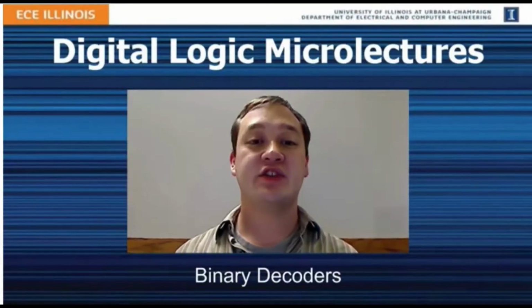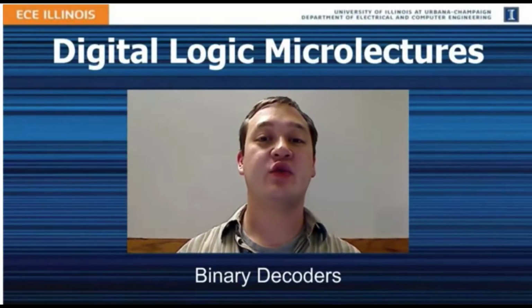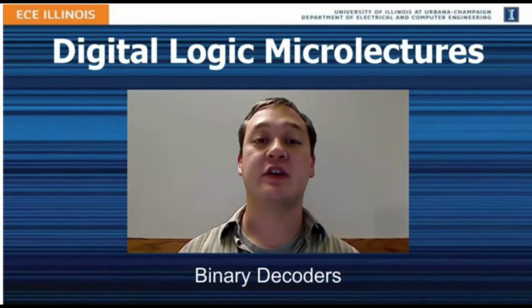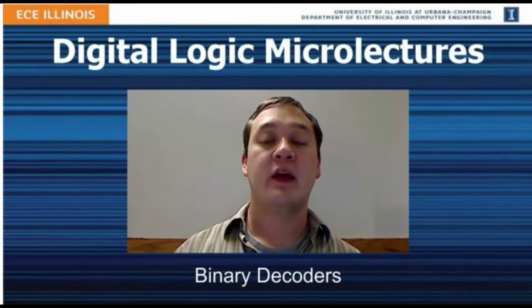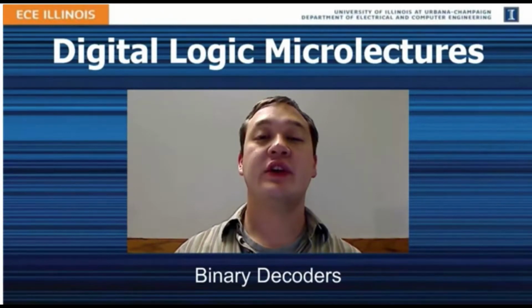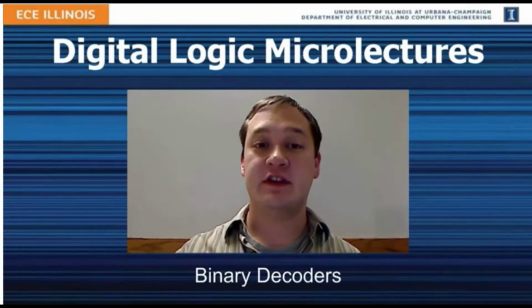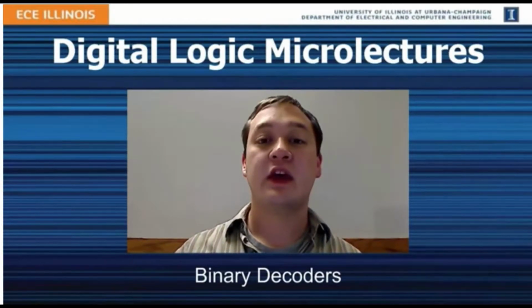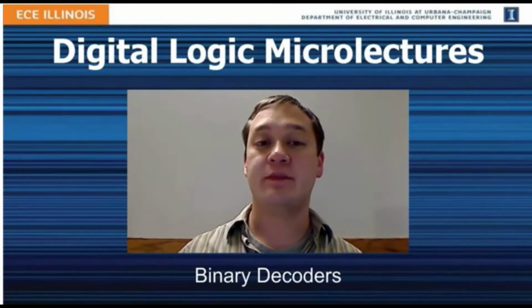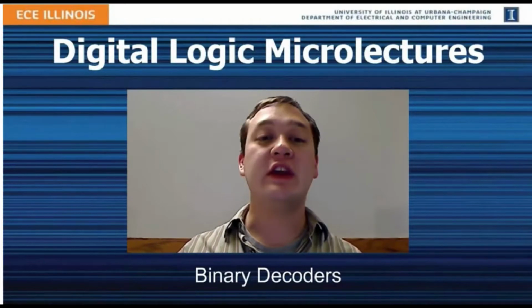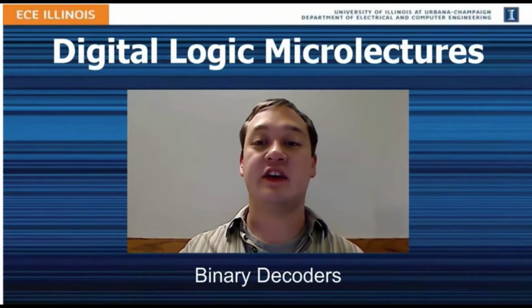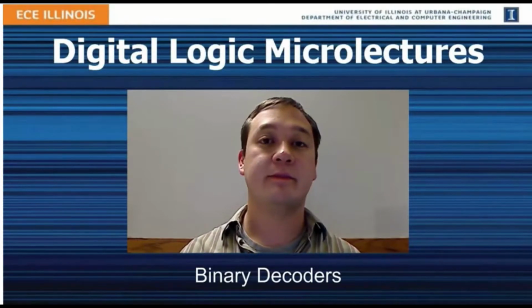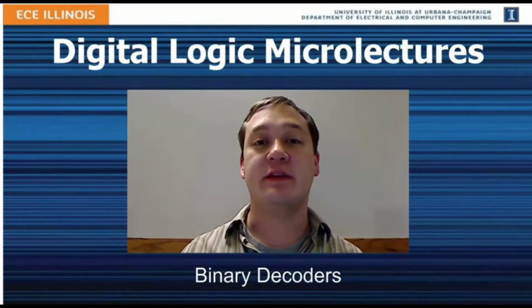When we design large storage devices, we need ways to quickly and easily retrieve information from specific locations in the storage devices. We create this retrieval system by storing information in chunks of bits that are stored at addresses, and we encode the details of these addresses within a binary code. So, we need a circuit that decodes these binary codes and activates one memory address at a time. This circuit is called a binary decoder.